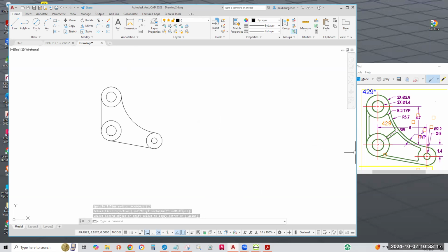Now, typically, the offset of these lines and arcs here are 0.3. So let's launch offset. Offset begins, set the offset distance. Quite different from fillet. I don't know why. 0.3, enter. Offset that guy inward, offset that guy inward, offset that guy in, out, in, out, in, out, inward.